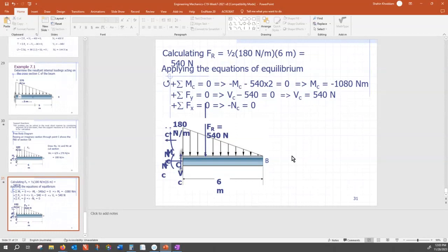And if you have managed to calculate the reaction, now the question is whether to take the free body diagram on the right hand side or left hand side. You follow the convention of positive assumptions. You put the forces in a positive assumption and then you solve. If you found the bending moment positive, that means the beam is deflecting cups up, like laughing. If the assumed convention proves to be wrong, that means at that point the beam is changing radius of curvature in a sad way.